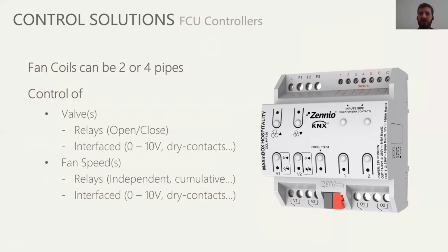So a fan coil controller. Fan coils, as said, are a system where you have a coil and a fan. You just bring that together in a fan coil. A coil with either hot or cold water, which would be a two pipe. So in a two pipe, you've got in the same coil either hot water or cold water.